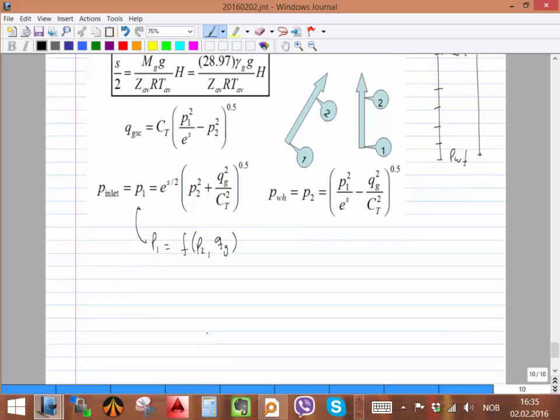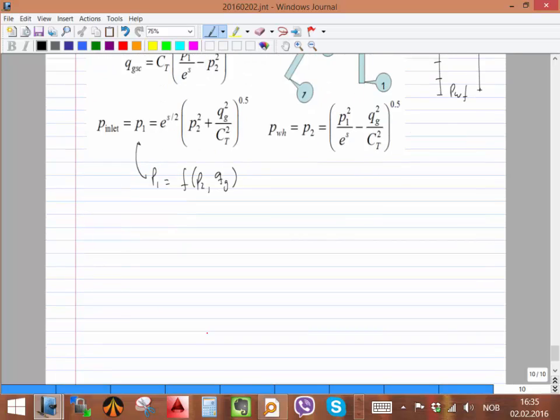Is that clear? Remember, I can use that equation, the same thing I told you at the beginning of the class. I can put the outlet pressure and the rate, and then I get what? The required pressure, the P1. Or I can put P1 and the rate, and I can calculate the available pressure, right? And that equation is valid for single phase gas.